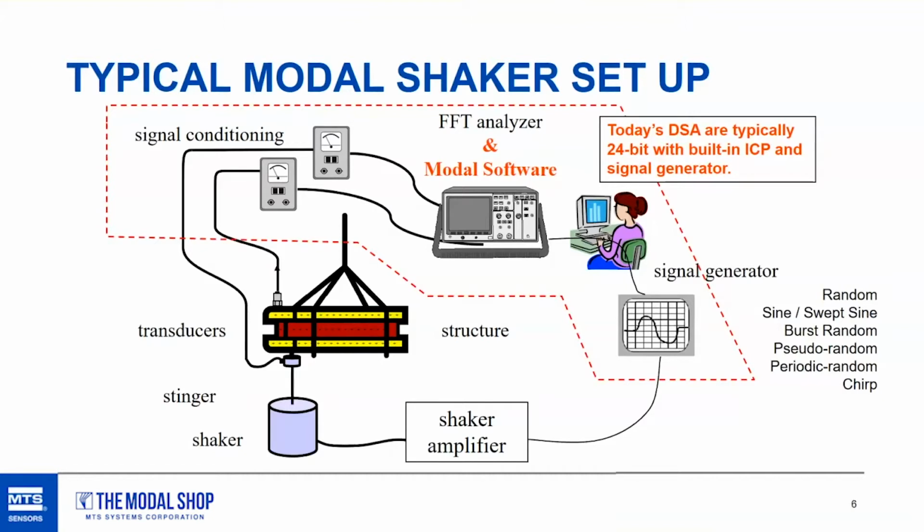So you're exciting the structure, and you have accelerometers mounted on the structure going into a data acquisition system through signal conditioning. A lot of times the signal conditioning is already built into the data acquisition.